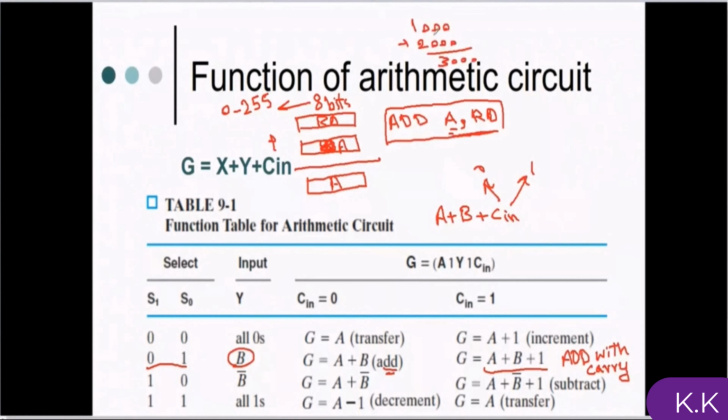You cannot add these 2 numbers by one instruction, but you can write a program for this purpose. For example, this is a 16-bit number, so you can consider it as 2 bytes, and the other one as another 2 bytes. Then the 2 lower bytes will be added together and compute one part of the result.